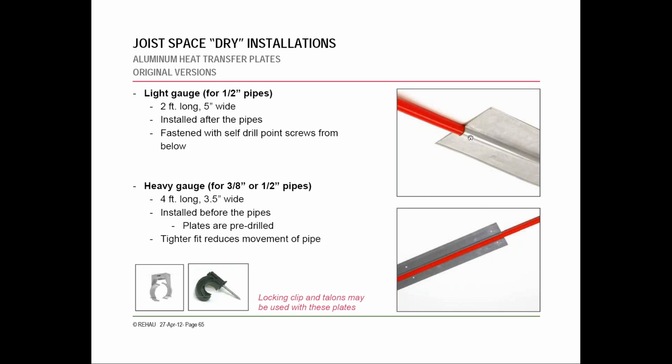Here are a couple of Howe's different plates. The one you saw in the picture before is the most common. These are some more standard ones. Or as I mentioned, you can clip them in directly to the wood. Less heat transfer. It will definitely affect the amount of heat you can get out of the system, but definitely another technique that you can use depending on how much your customer is willing to spend and what's existing.